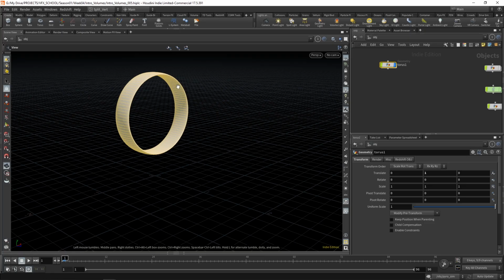And let's animate it to rotate. Okay, we'll go here to the rotation on the z-axis and say time times 90. Okay, time times 80. So now it rotates. Probably go faster. Let's say 120. Okay, something like that.